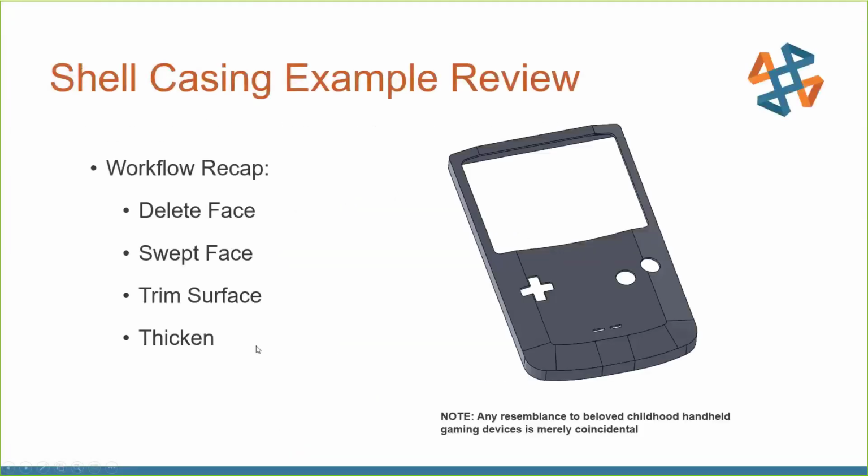So just to review, we used delete face to transition from a solid to a surface body. We used swept face to add a little more detail with a beveled edge, and then trim surface to clean everything up. And then we thickened our end result.